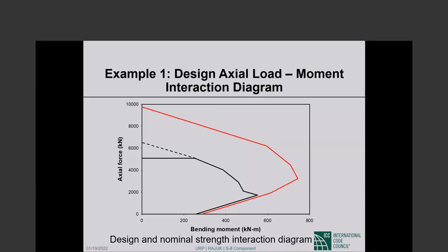And even when not required, it is not a bad idea to do that. You don't have to go too deep, but something like 12 inches is a good idea. Sometimes it is 12 inches or one development length of the largest longitudinal bar, however much that is. So in the seismic area, there are specific requirements. Non-seismic, there is no particular requirement. But depending upon what you are building, it may not be a bad idea to continue it for a little bit.